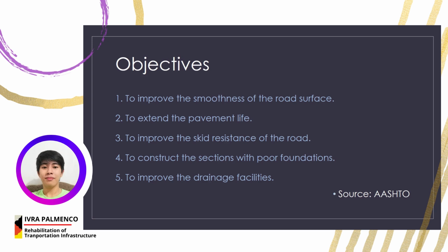For number four, to construct the sections with poor foundations. Constructed pavement foundation layers often have isolated areas of poor quality that are believed to contribute to localized pavement performance issues. That's why it is important to properly integrate sections with unstable or poor foundation conditions.